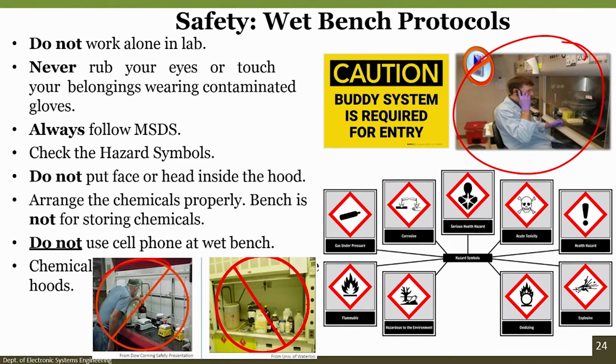Next thing is you should never put your head within the wet bench, because there is a vapor from the boiling of the chemical, and we will breathe in that vapor if we have the head within the wet bench. So, you have to take care of these issues while working in the wet benches.